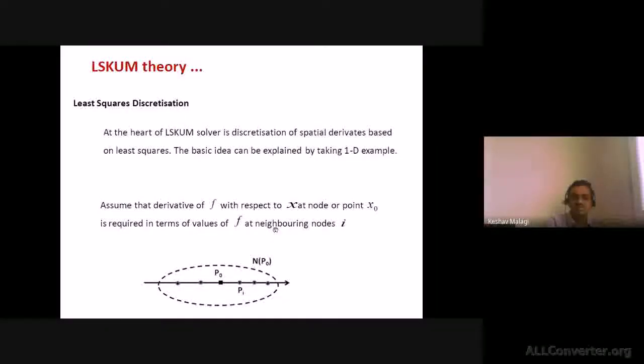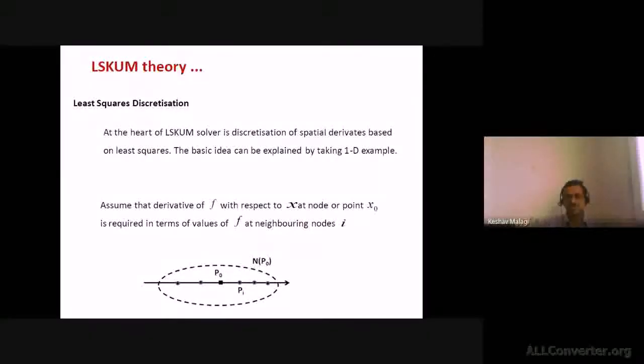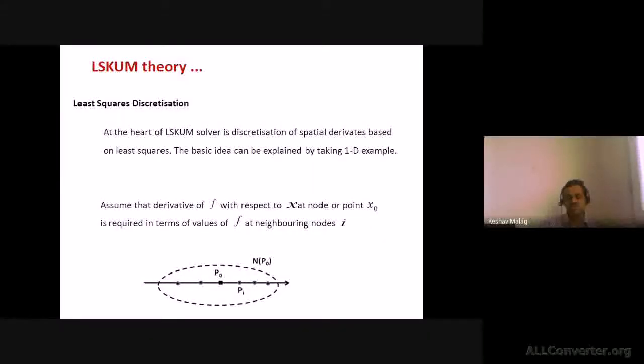Okay, so at all the points in the domain, you have the value of f given to you, and you want to obtain the value of the derivative. You remember the Euler equation, the Navier-Stokes equation, you will have these derivatives appearing, right? So here we are trying to evaluate the derivative for a given function f. Once we are solving those equations, we will have to define this f to be the fluxes which are defined there.